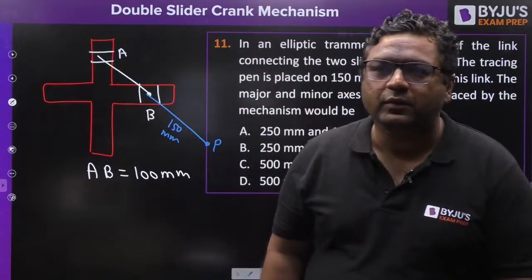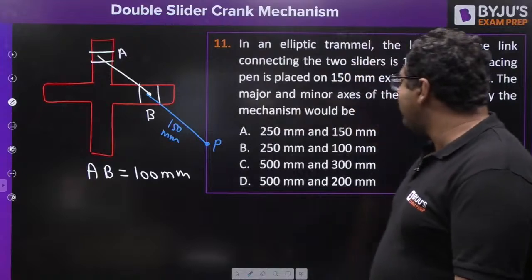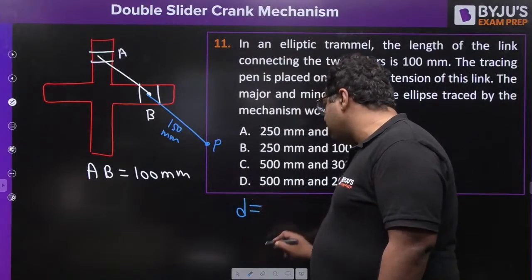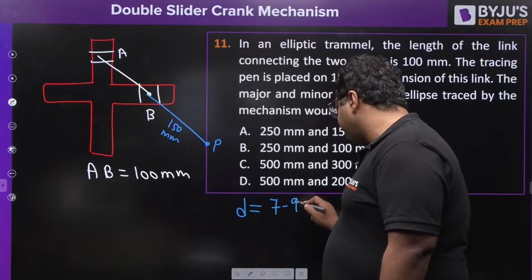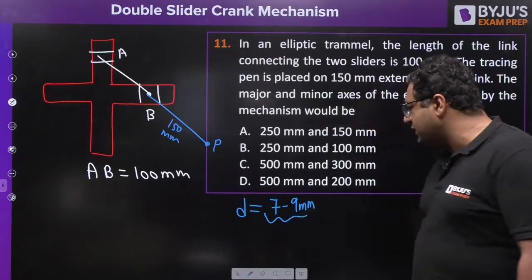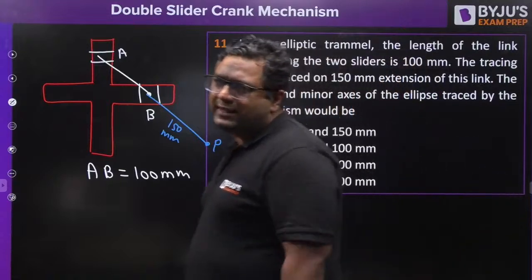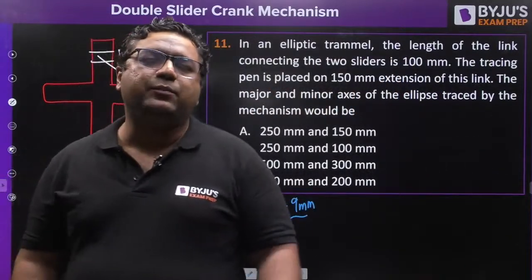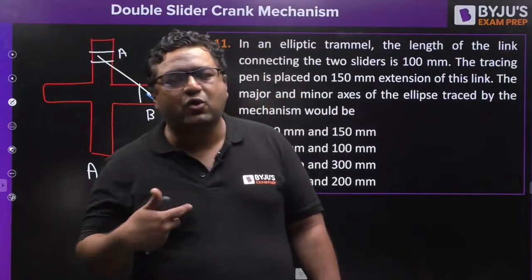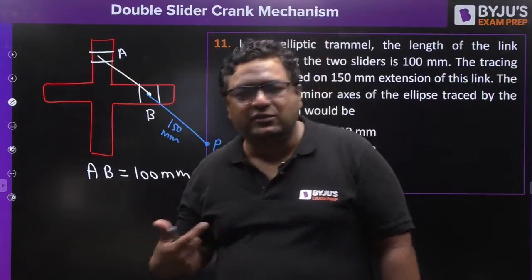Anybody? Okay, very good, Abhimanyu. You have asked a very good question. I would like to say the maximum offset permissible is 7 to 9 mm. Actually, that is the general value. We can have slightly more than that also, but we are keeping it less because when we have more offsets, my dear, the chances of losses would be more.